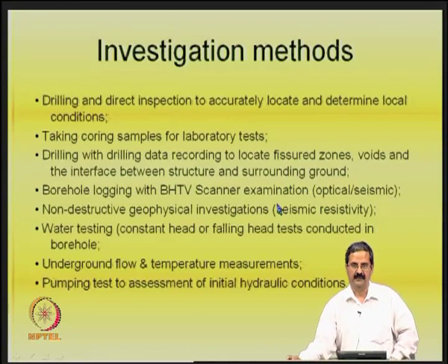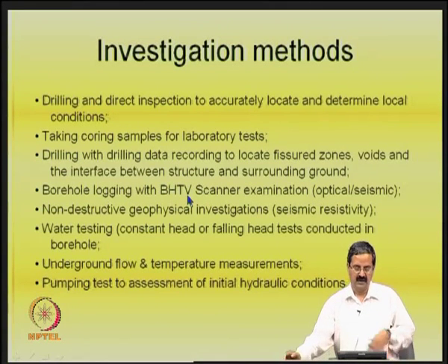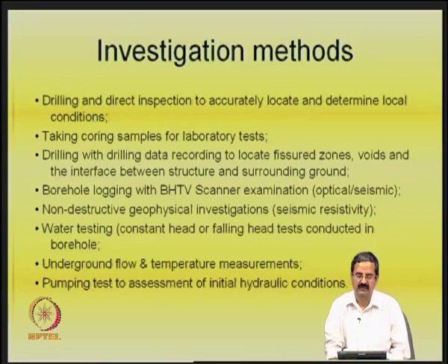If you are trying to look for underground problems or issues, even nowadays you have borehole cameras which can give you information about the type of soil that exists. People are also employing non-destructive geophysical investigations, seismic, resistivity, then water testing.